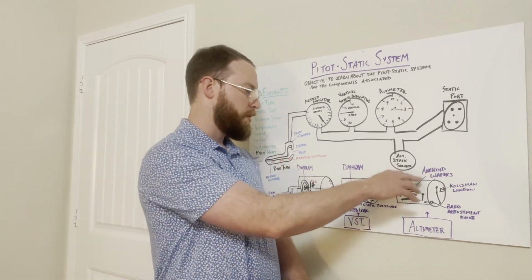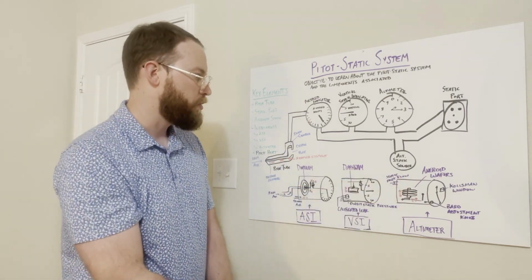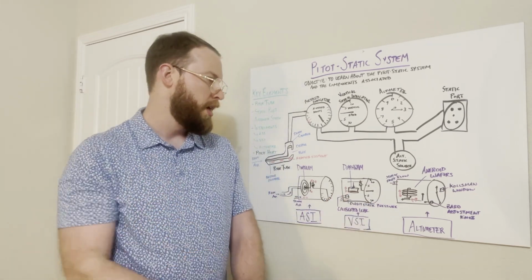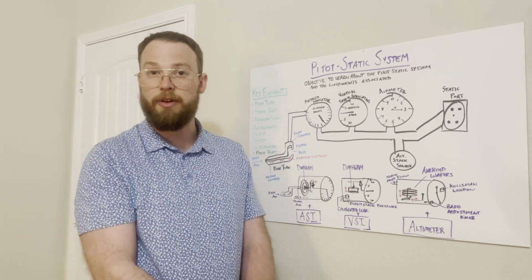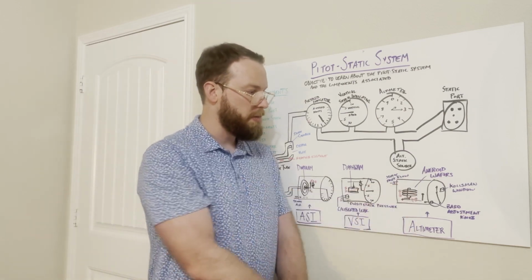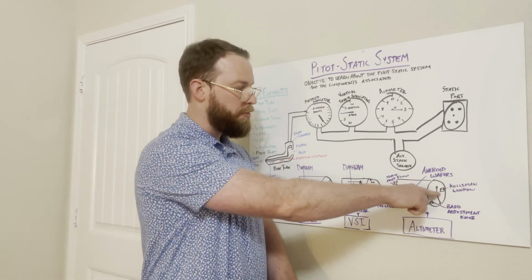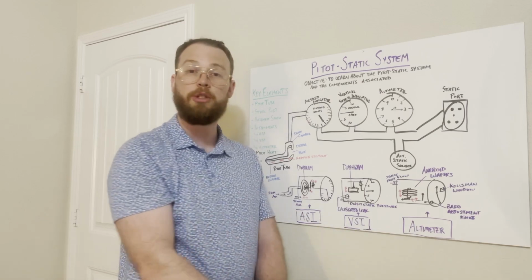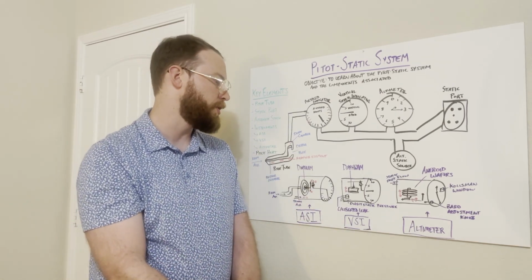MSL. Now, looking at our diagram here, we have a stack of aneroid wafers. This is a little bit different from the other 2 instruments because these aneroid wafers are sealed and already set and adjusted to standard atmospheric pressure of 29.92. What we can do that's different on this instrument is we have a manually adjustable barometric knob where we can set our pressure, and then view that in what's called the Kollsman window, which shows our current pressure setting.